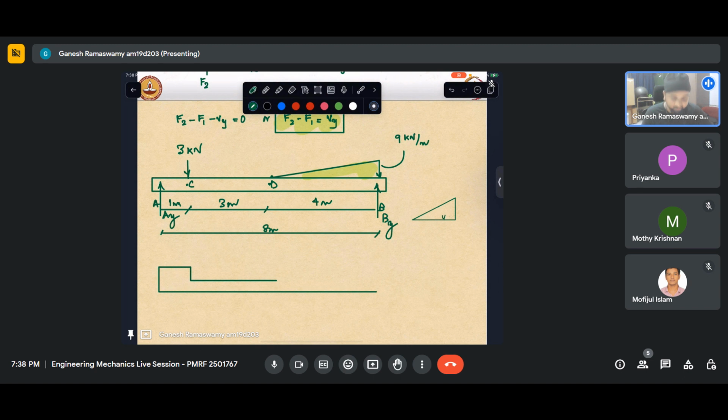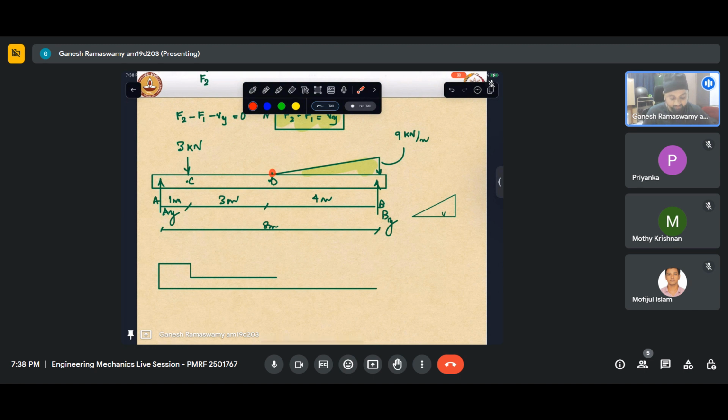And then as I take section from D, as I keep on taking section, I just need to account for that much of area and subtract it out of my equations, with the understanding that at D, the triangle is 0, which means at D I will have a unique value. There won't be any jump. So at B, can I calculate?